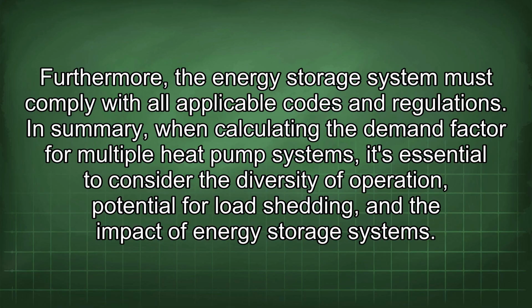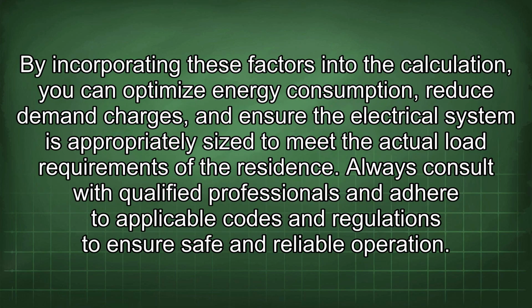In summary, when calculating the demand factor for multiple heat pump systems, it's essential to consider the diversity of operation, potential for load shedding, and the impact of energy storage systems. By incorporating these factors into the calculation, you can optimize energy consumption, reduce demand charges, and ensure the electrical system is appropriately sized to meet the actual load requirements of the residents. Always consult with qualified professionals and adhere to applicable codes and regulations to ensure safe and reliable operation.